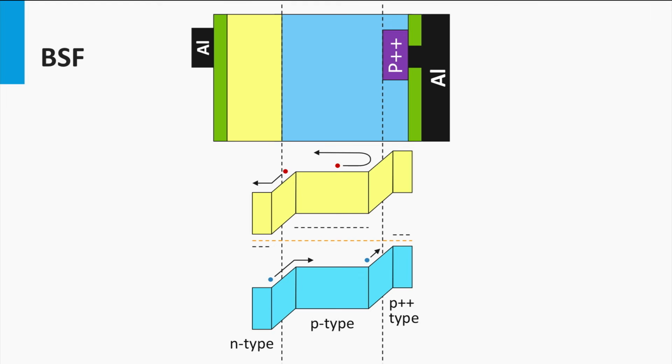In this case, it will act as a barrier for the light-excited minority electrons in the lower doped region to diffuse to the back surface. The space-charge field behaves like a passivation of the defects at the back contact interface and allows higher levels of electron minority density in the p-doped bulk.